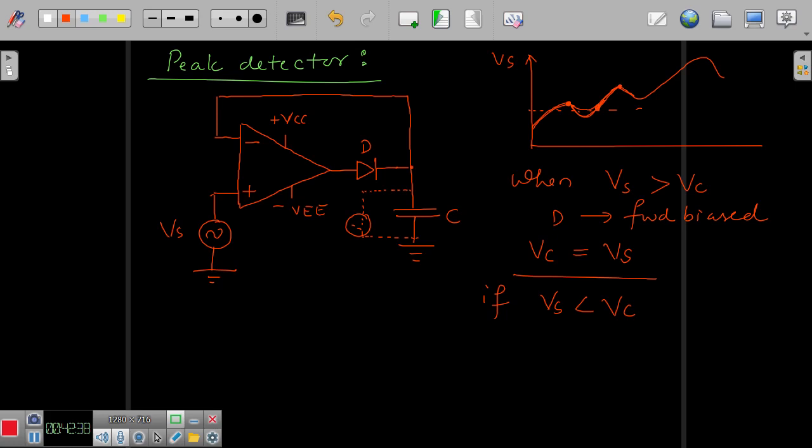Now once it comes down, then again the voltage will be held here, and it keeps repeating till you have the maximum voltage recorded as per the capacity of the input voltage as well as the capacitor. You cannot have an indefinite value of the voltage, right? Here they are all physically limited by these things, right? Now suppose you want to measure one more value. Let us say here I have got one more peak, something like this, right? It is not possible for us to measure this because the voltage is already clamped to this value.